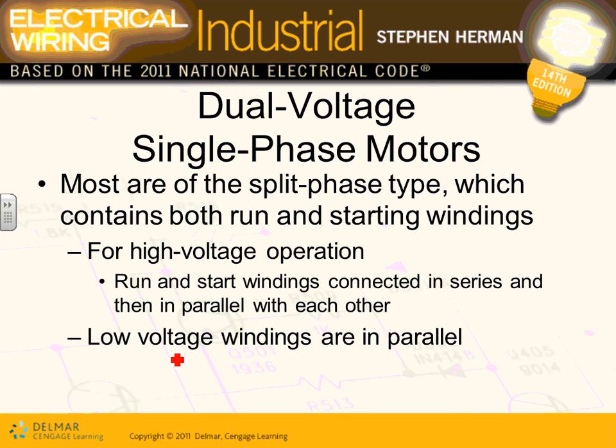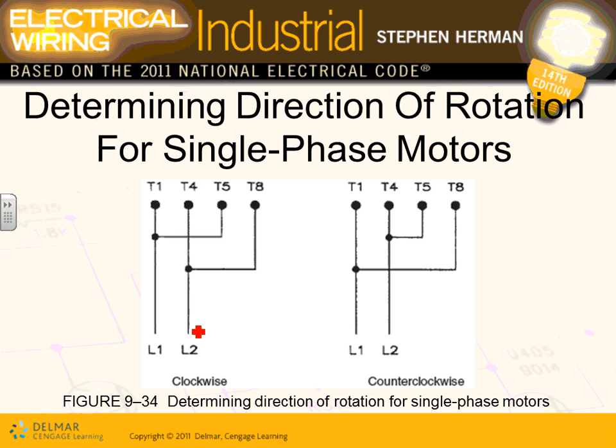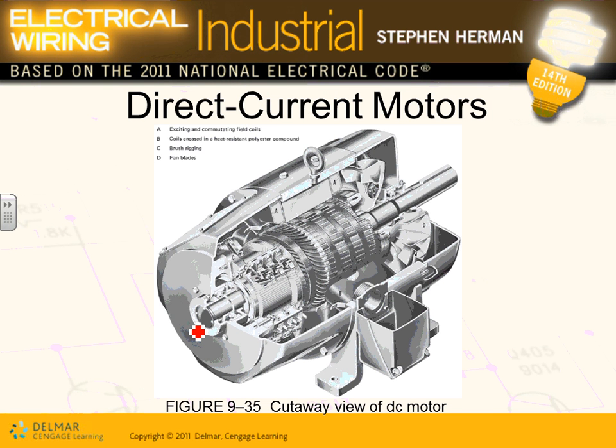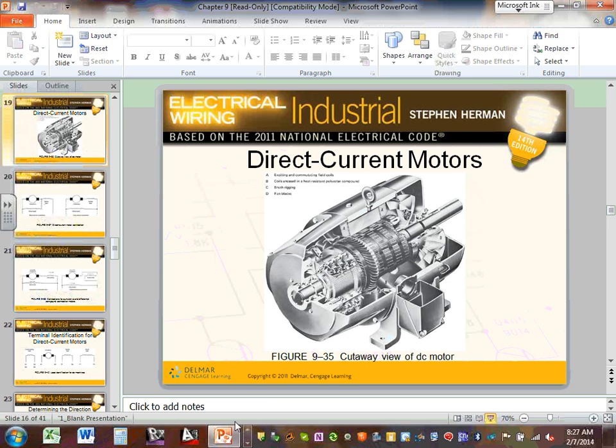Now, moving on. This is three-phase. We talked about Y and delta, high voltage and low voltage. In single phase, guys, it's the same thing. There's something called a split phase motor. You wired it many times with us, and a lot of you guys wired it in our labs. You can have high voltage or low voltage operation based on how you connect them. When you connect high voltage, here's the connection for clockwise and counterclockwise. We'll talk about that. Let me go directly into a couple of pictures here because they're easier.